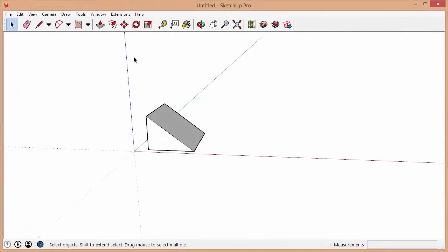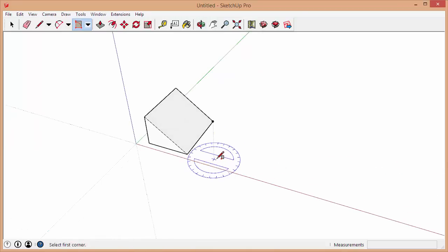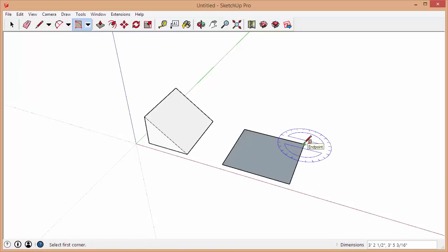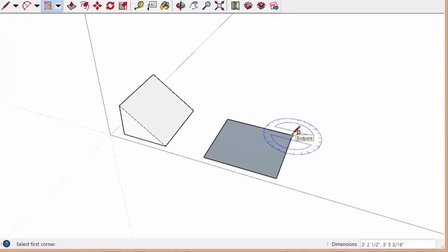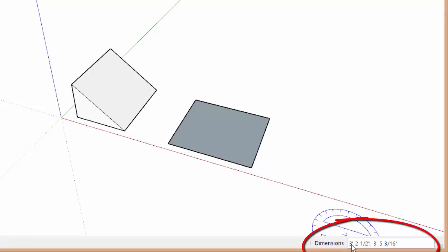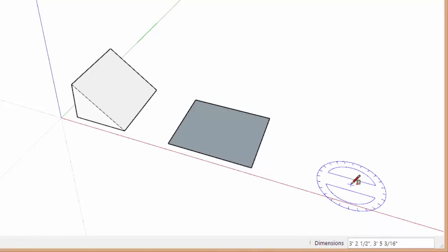Another thing that's really powerful about this tool is your ability to control the size. Now, like a lot of tools in SketchUp, when you draw something, you have the ability to define an absolute size for the object. So if you look down here, I just finished drawing the rectangle, and you can see I'm at this arbitrary size. So if I just type in my own dimension, I'll go 5 inch, comma, 3 inch, and when I tap enter, you can see the